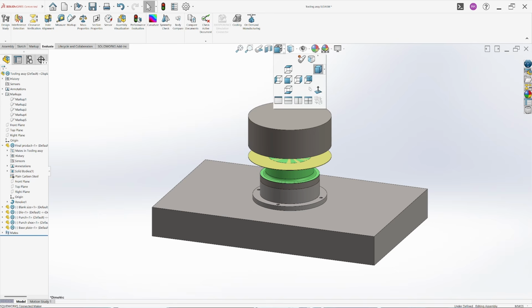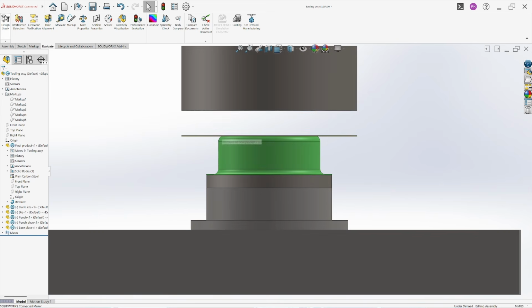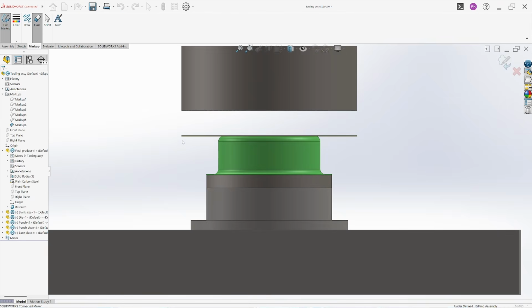So what would be the diameter of the blank holder? So we are going to design our blank holder. Let me take another color somewhere here. The outer diameter of the blank holder will be equal to the diameter of our blank size, which is 280 mm, and the inner diameter should be the outer size of the punch, which is 200 in this case.